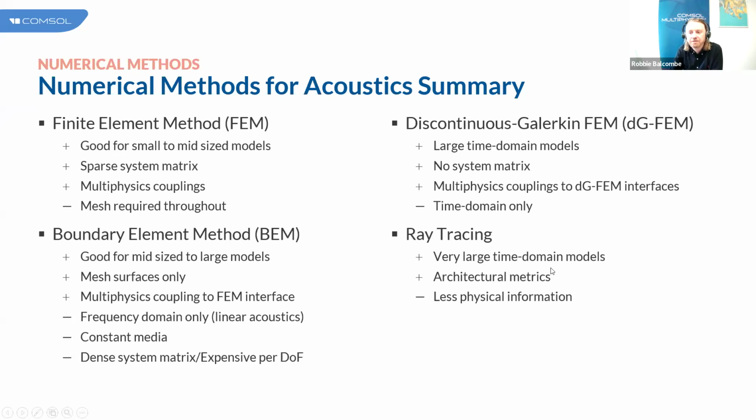And then finally, we have the ray tracing method. So this will be useful for looking at large to very large time domain models. So underwater acoustics, architectural acoustics, and also environmental acoustics. The drawback here, though, is that we will get less physical information in our results. So essentially, it's a lower fidelity approach, but allows us to go to larger geometries or higher frequencies.